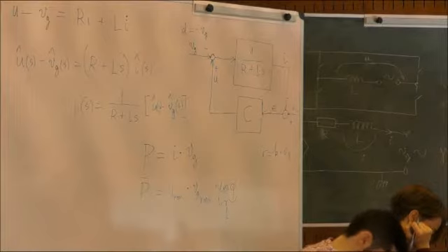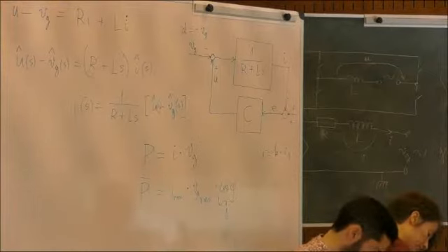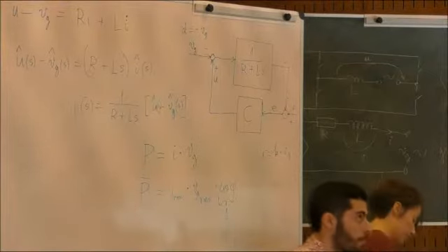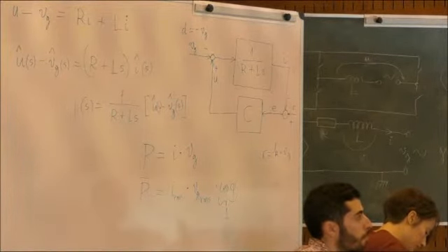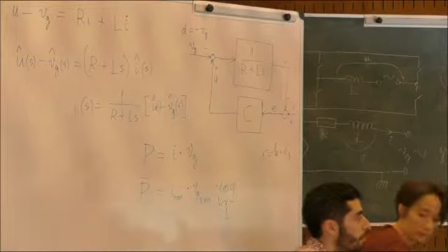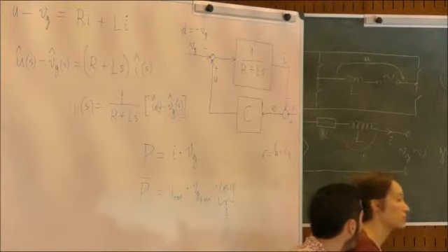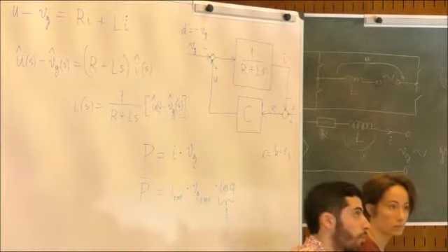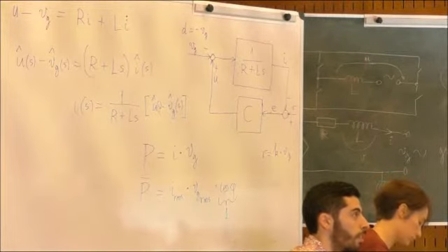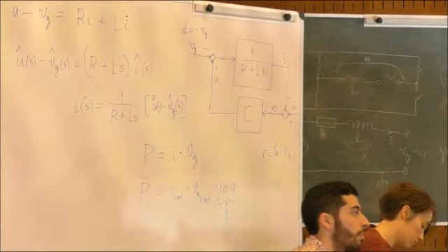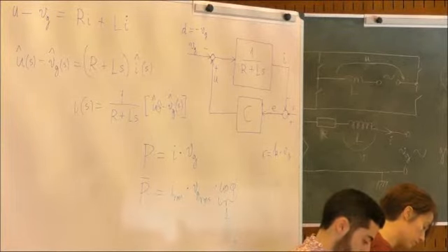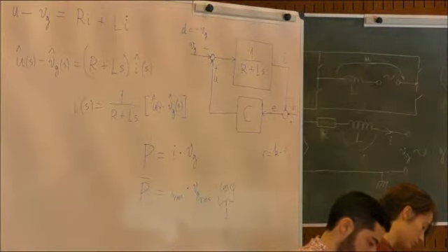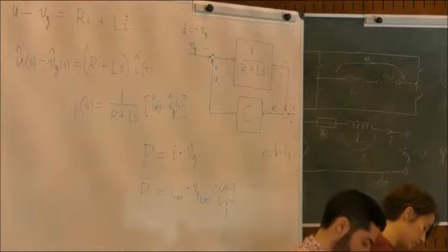Now such a device is called a phase-locked loop. Yes, I mentioned earlier today a phase-locked loop. So a phase-locked loop, first of all, from a mixture of several approximately sinusoidal signals, extracts only one, and you can hop from one to the other. You can choose which one you extract, but in the case of the grid, it's clear which one you extract. So you extract one of them, and then from this one, you extract only the fundamental component in the Fourier series.